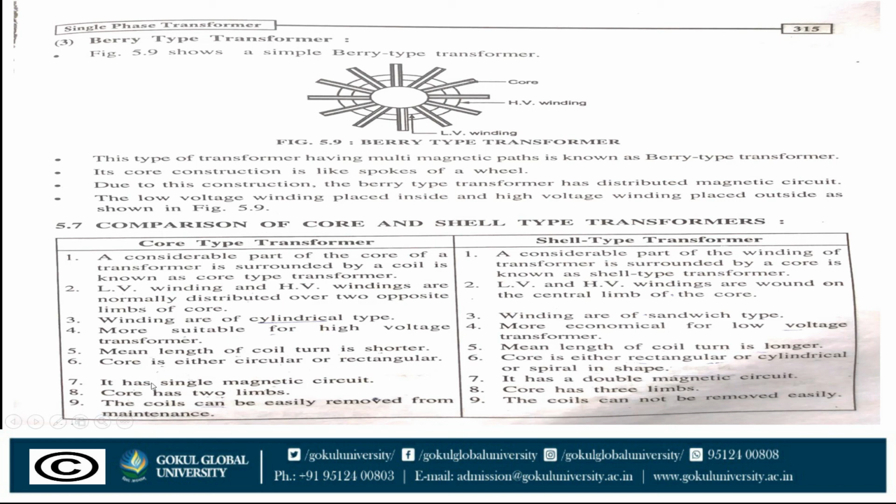In core type transformer, it has only a single magnetic circuit, and in shell type transformer, it has a double magnetic circuit. In core type transformer, core has two limbs, and in shell type, core has three limbs. In core type, the coils can be easily removed for maintenance, and in shell type transformer, the coils cannot be easily removed for maintenance.